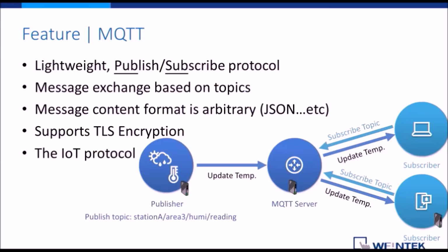And when you make it bigger and bigger, that's your MQTT network. Some key points are that the messages are based on topics. The message can be arbitrary, which the IT people will definitely like. And it is also secure because it supports TLS encryption. So security is not an issue, even for MQTT.